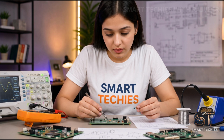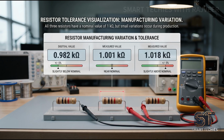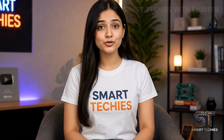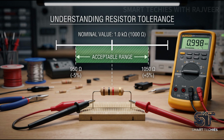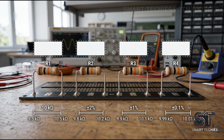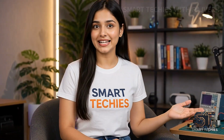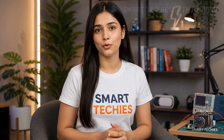A resistor's printed value is not always its exact real-world value. For example, imagine a resistor labeled 1 kilo ohm plus or minus 5%. This means the actual resistance can be slightly higher or lower than 1 kilo ohm. This allowed variation is called tolerance. Common tolerances include 5%, 2%, 1%, and even much smaller values for precision resistors. A smaller tolerance means the resistor's actual value is closer to its specified value.